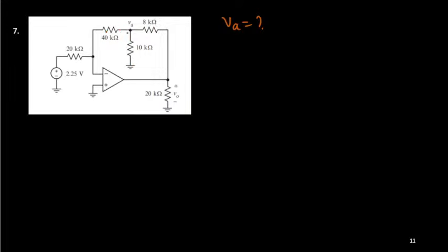So you have a T network connected here instead of one single resistance that provides negative feedback. But anyway, this is connected to the negative terminal, the inverting terminal. Thus, it is complete, so you are getting negative feedback. Because of that, you can assume that the output voltage will be finite.